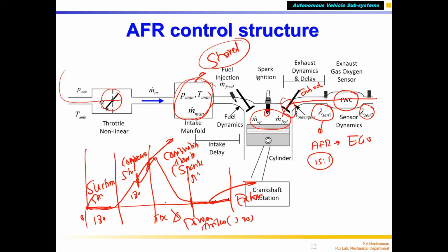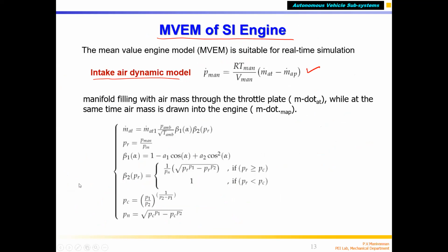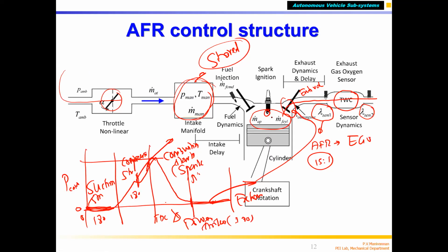During this time, the exhaust valve opens and the hot combustion gas is thrown out. So this valve opens. Here you can see that the pressure will be less, below 1 bar. We are talking about the pressure inside the combustion chamber. During the suction stroke, the combustion chamber pressure will be low, below 1 bar. Only then will suction happen. When the piston goes down, a vacuum is created, and you can see the pressure is shown lower than 1 bar. That's why air is going in.